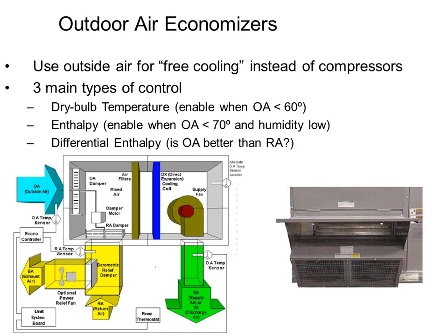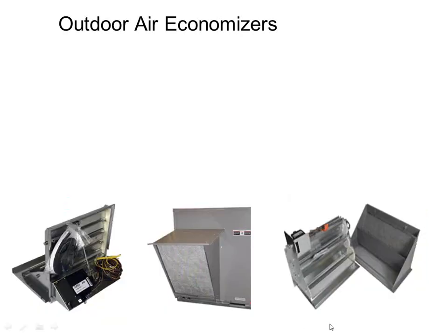So above 15 tons, definitely go enthalpy. Below, I'm going to say 6 tons, go dry bulb. And in between, we can argue about in between depending on how big or how many hours the system is going to be running, right? And who's going to be maintaining it.